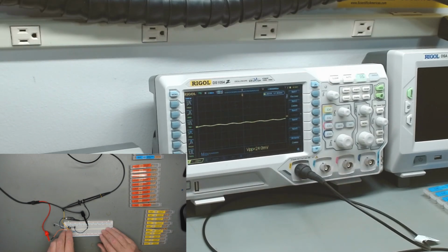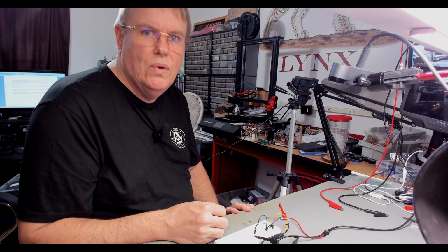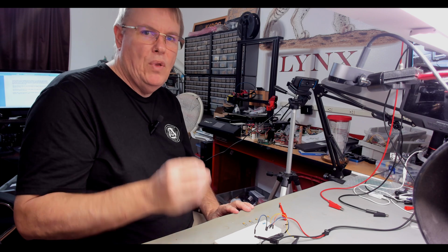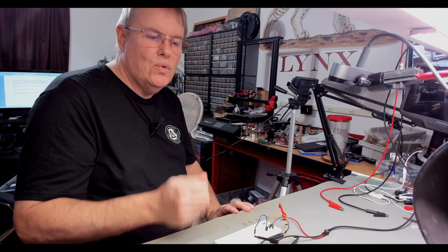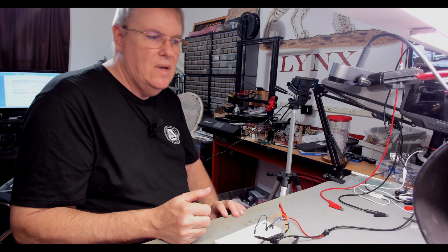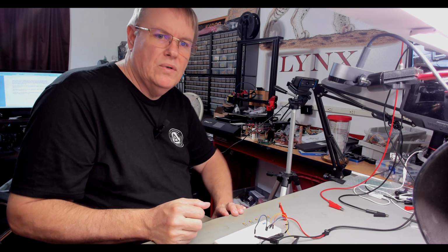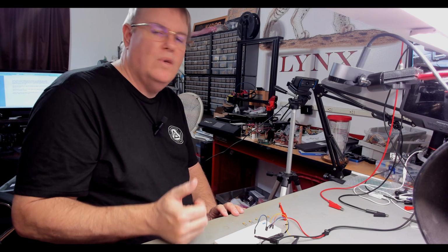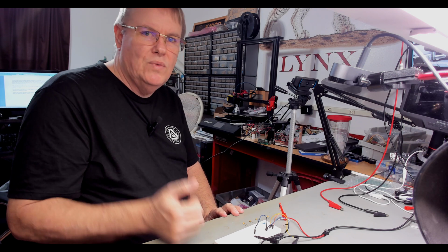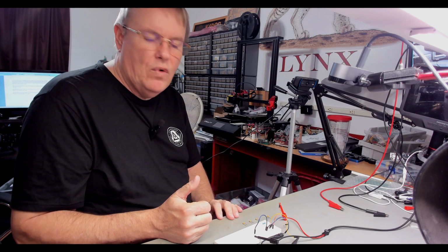This is what was happening in that little module. The capacitors were much too low a capacitance, so they were blocking the frequencies. We had to increase the value to allow those lower frequencies to pass. They would have worked great at your higher frequencies. Above 500 megahertz, they would have been great. But unfortunately, we weren't working in that frequency range. So we had to change those capacitors to allow our signal to more freely pass through them.